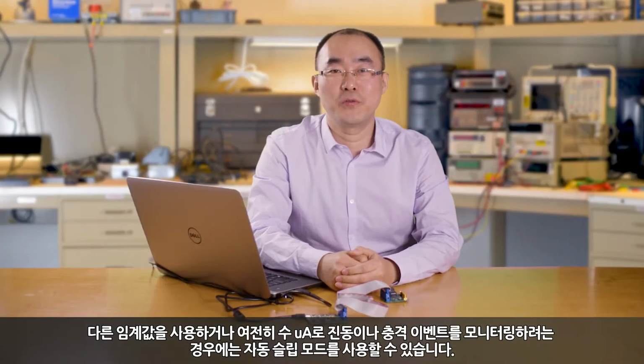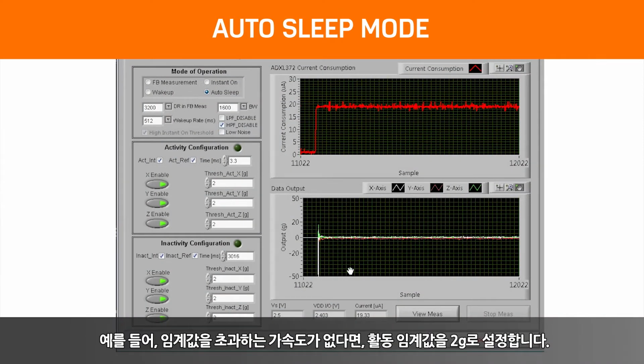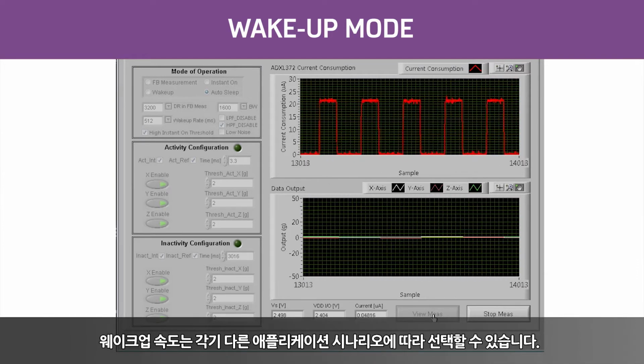If we want to use another threshold and still monitor vibration and shock events with just several microamps, the auto-sleep mode can be used. For example, set the activity threshold to 2G, then when there is no acceleration over the threshold, the ADXL372 will work in wake-up mode, and wake up to sample the acceleration every specified time. The wake-up rate can be chosen according to different application scenarios.